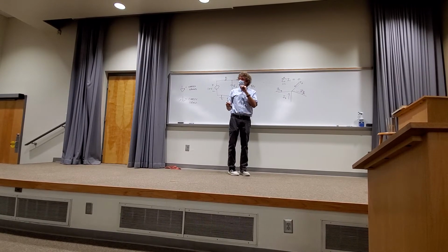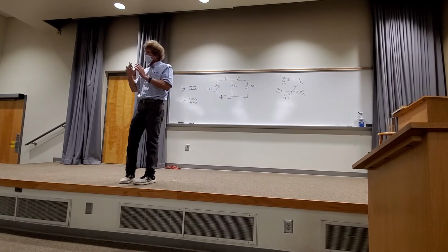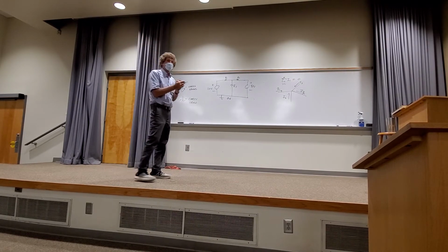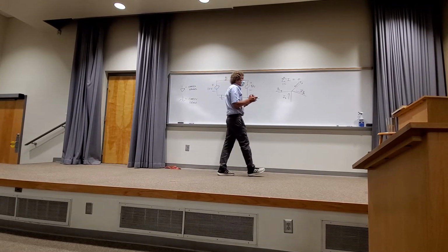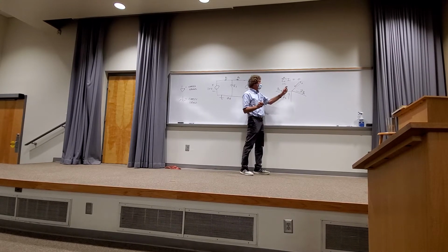The reason I'm doing it this way: think of current as an incompressible fluid, if you're an ME. It's not like air where you can pressurize it and it can go through phase changes and there can be a whole lot of it or none of it. Anything flowing into this point has to flow out. You all follow me on that? That's what I'm getting at with this law.